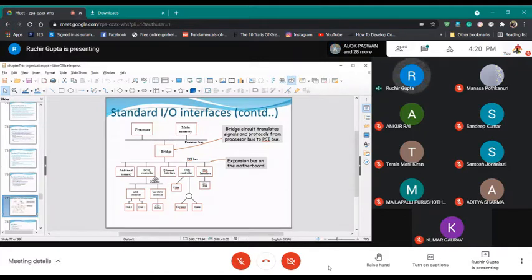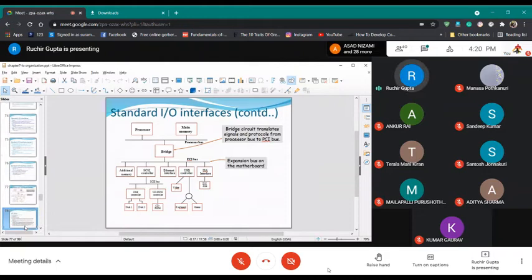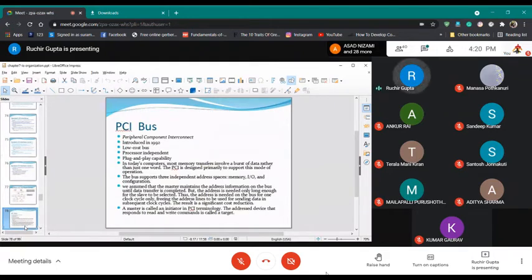The second more important thing is that the PCI bus is not designed for single byte transfer. It is basically designed for burst transfer. So there will be a large amount of data that will be either read or written somewhere, and the PCI bus is designed for this. Even if there is a single byte to be transferred, that will be considered a 1 byte burst.